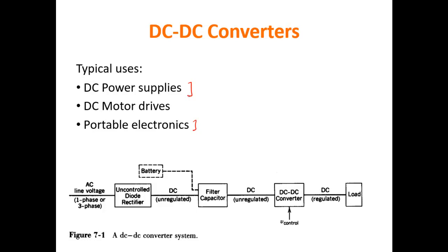And another very typical use of them is as a motor drive, because typically the way to drive electrical motors is to modify the supply, to adjust the supply voltage provided to them. So by adjusting the supply voltage, you modify the torque or the velocity or also the angle of an electrical motor, and therefore they're widely used to drive electrical motors.